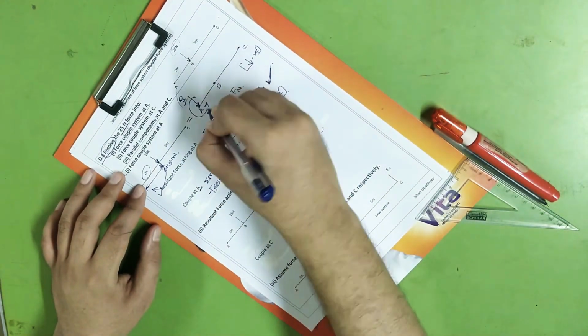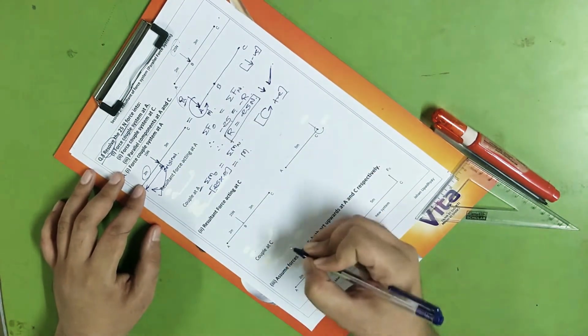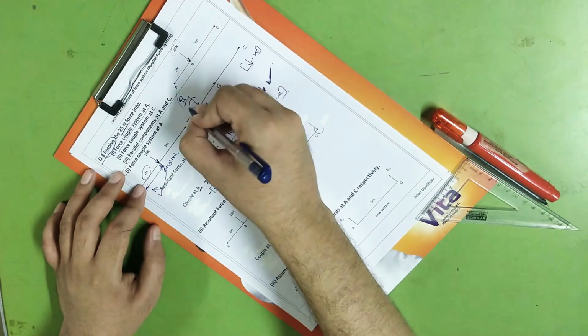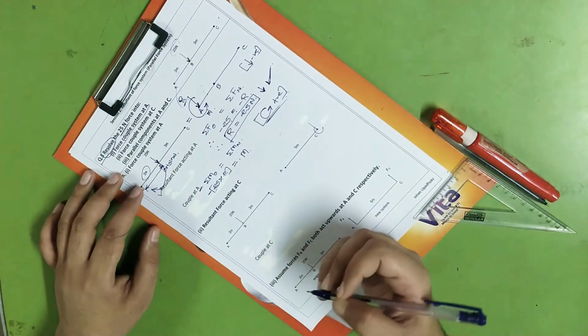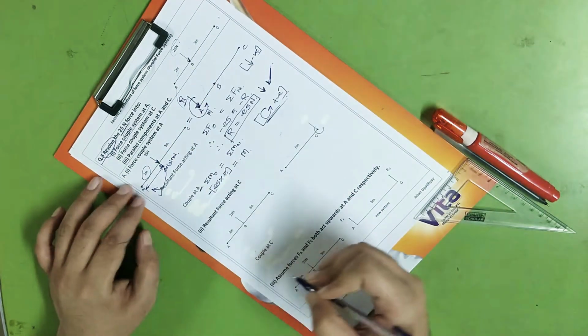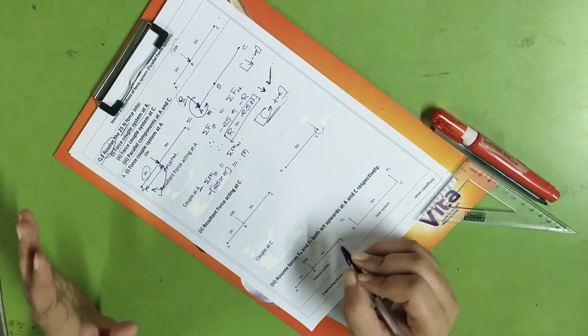First is resultant force and next is a moment. First let me copy paste the moment, so I'll say M. I am not putting a negative sign over here because I have assumed that M is in anti-clockwise direction and anti-clockwise is taken as positive. Next is force R, and we know very well that forces that are passing through the point about which I am taking moment will give me what?